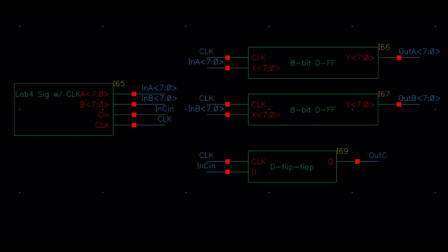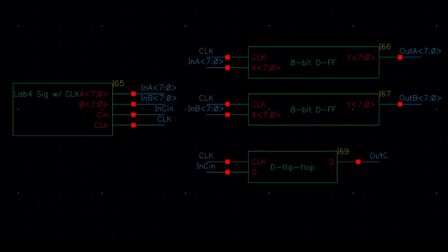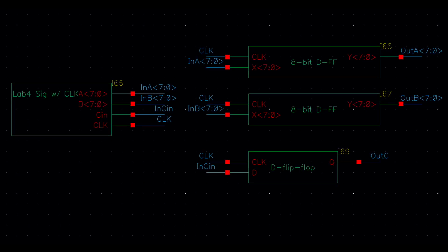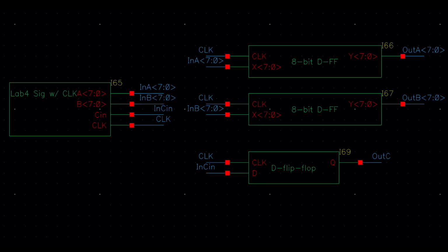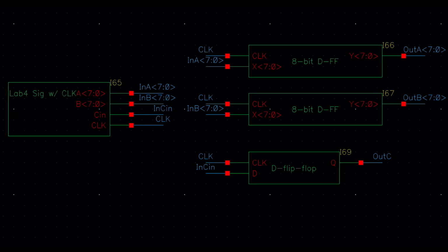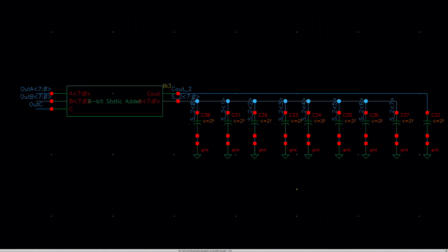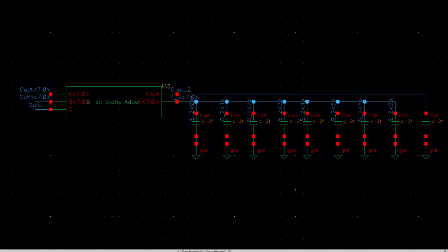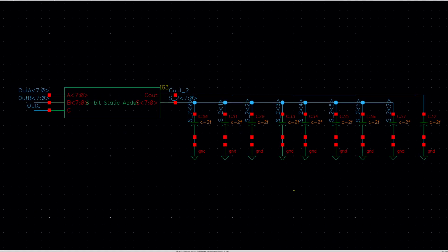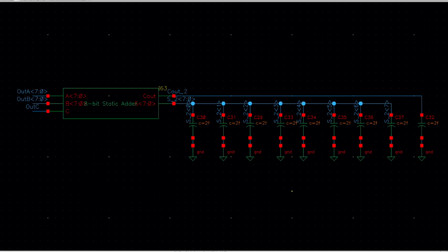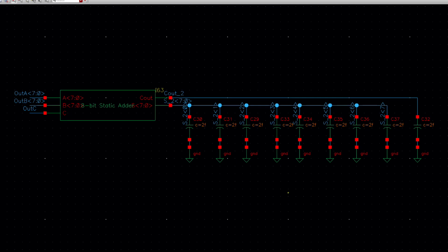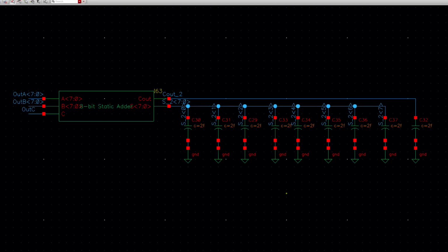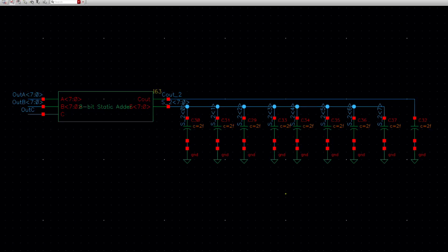Also, you can note that this is how you declare multiple-bit buses in Cadence Virtuoso using the same MSB to LSB designator that we used in Verilog-A. The outputs from the buffer stage feed into the adder shown here, and you can read each of the outputs as such by destructuring the bus. I won't go into the specifics of how to design the adder, but this is in general how you can read the voltage outputs at each of the 8 bits of the adder.